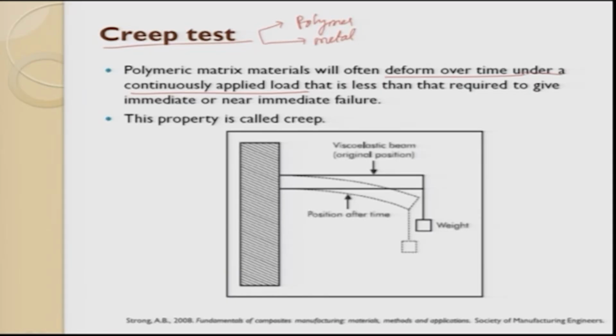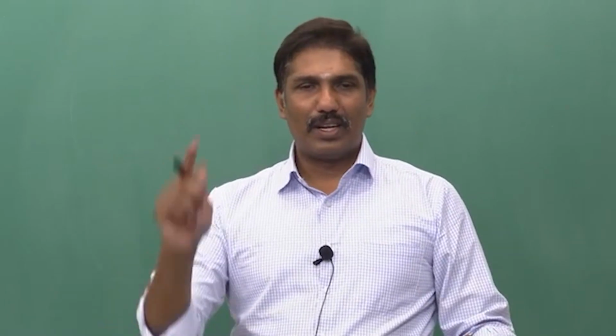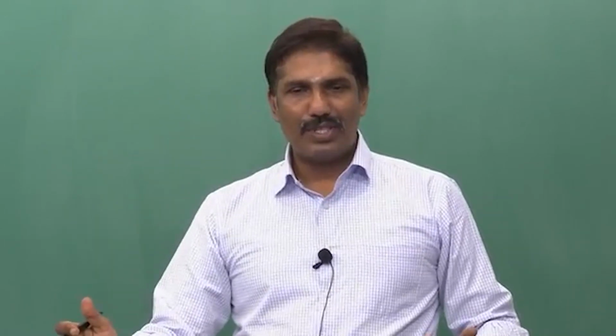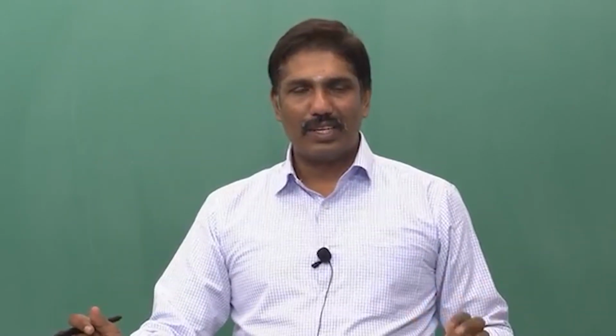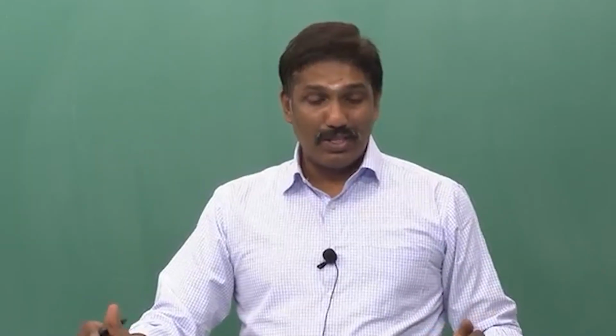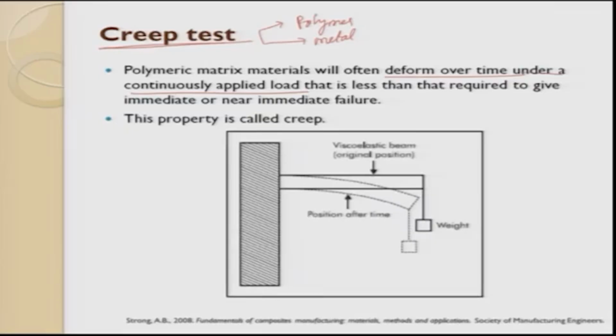A pot will be attached with a thread and that will be attached to a hook. All of a sudden the pot falls down and gets shattered. Why? Because the polymer undergoes expansion. So this property is very important when you try to hang a load for a longer period of time. So this test will reveal the values which can be used for applications.